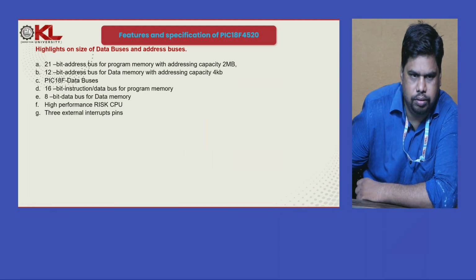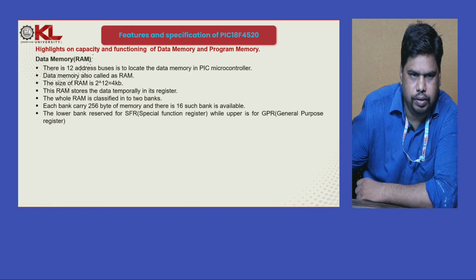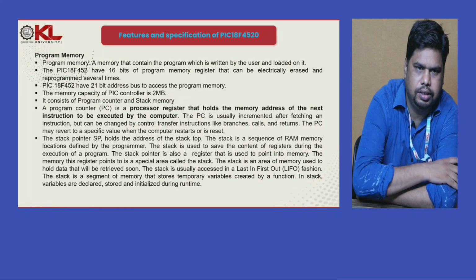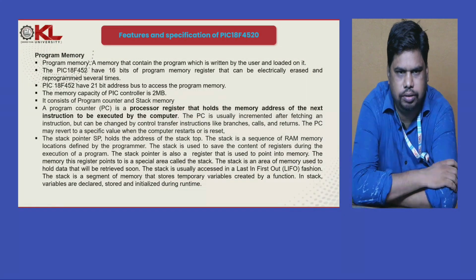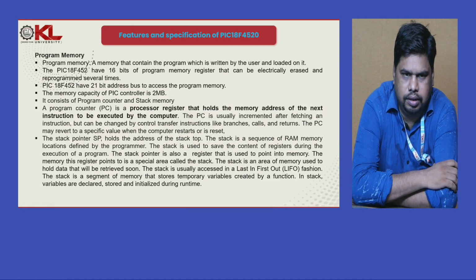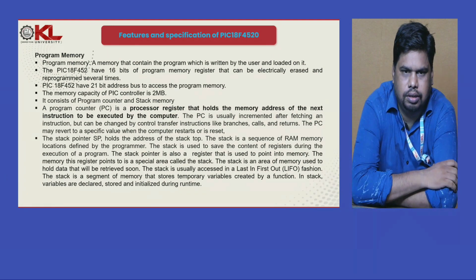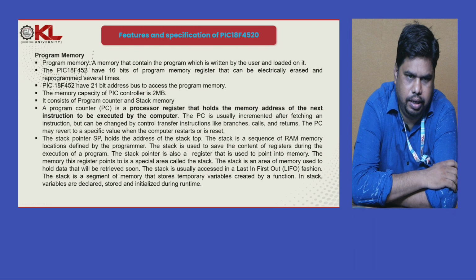Now I will go to program memory. What is program memory? A program memory contains the program which is written by the user and loaded on it. The PIC 18F452 has 16-bit program memory registers that can be electrically erased and reprogrammed several times.